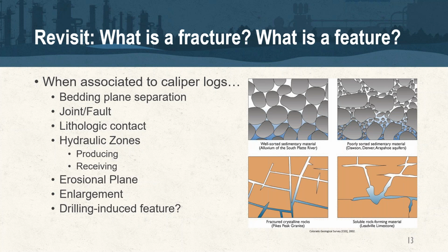And in some cases where we may not have favorable areas or zones, or maybe we don't have a lot of features or fractures, or they're very tight, undeveloped. Maybe we have a lot of secondary porosity. Those are places where, as Bill mentioned in his example last week, we're going to walk the packer up and down the hole in a pilot phase potentially, or if it's a small scale, small site, a full scale phase as well, trying to determine where we were unable to determine through those processes, geophysics and discrete sampling, if there may be ability to inject. So we'll focus on that in an example coming up.